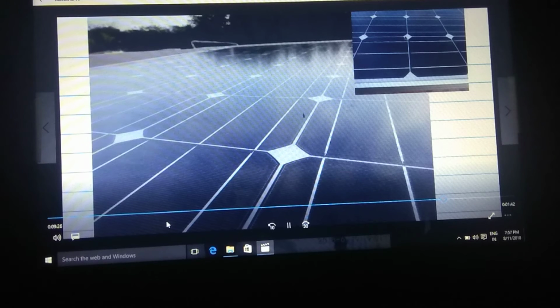Now, all these areas are not effective area, and the solar insolation, even if it falls on this area, is actually not captured. Therefore, the entire module actually has a bigger area, accommodating all these gaps and spaces, as compared to the pure cell area alone. And therefore, the module efficiency is definitely going to be lower than the cell efficiency.